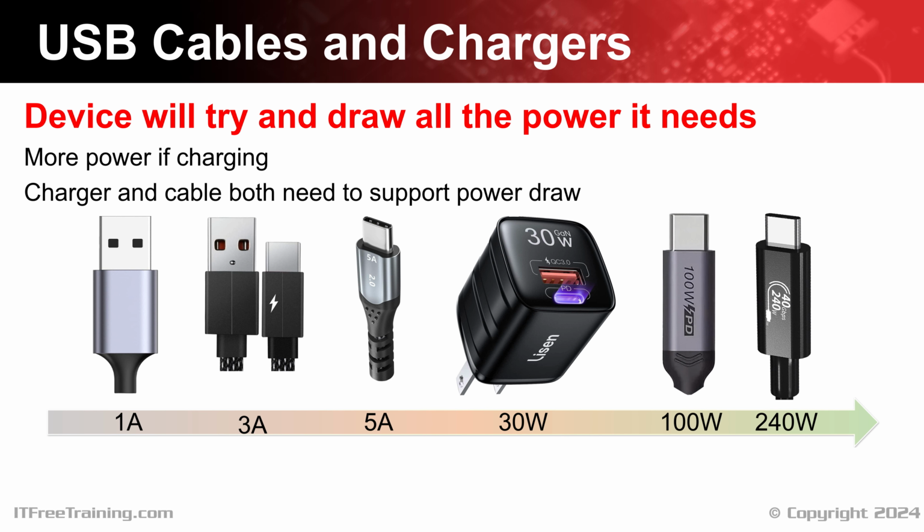A 5-amp cable should work fine since only the voltage is increased, unless the cable is poor quality. The next cable will generally be rated for 100 watts. A 5-amp cable can handle 100 watts, unless it is poor quality, in which case it won't be able to. The 30-watt charger is essentially saying it will output a maximum of 30 watts. This is good for some mobile devices which can pull a lot of watts when they're charging. Thus, a 100-watt cable and a charger with a lower output works quite well. If you use a cable that's not rated high enough, your fast charger capacity may be wasted.